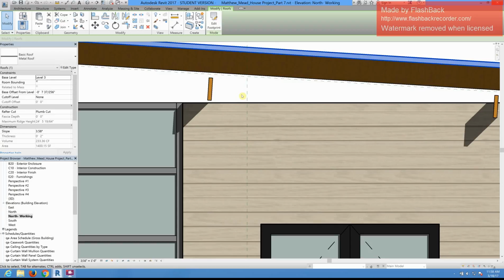the two reference planes, we offset it 10 inches, right? We offset it 10 inches. Well, these beams are 2 by 10. Now, if you've worked in construction, you know that a 2 by 10 is not actually 2 inches by 10 inches. It's actually 1.5 by 9.5 inches. So that's actually why you're seeing that little bit of a gap there.